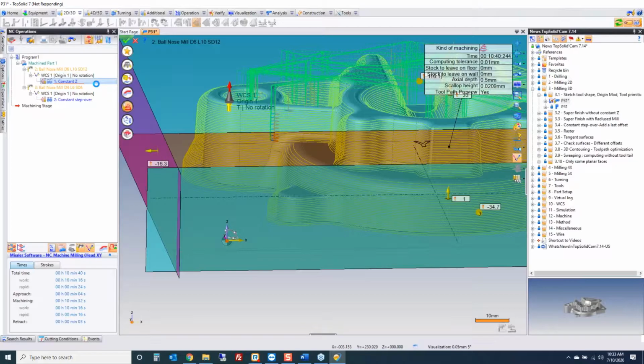Now what happens when it avoids everything is that angular shank is going to come close to touching right up here. And what you can do then is in that tool definition area, you can basically, let's call it, lie about what the actual shank of the tool is. So you can add some clearances in different places of the tool.